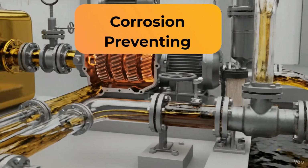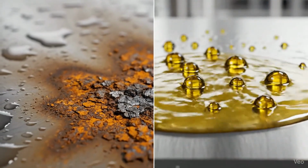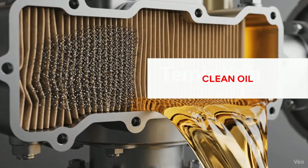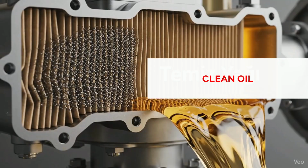Corrosion prevention. Oil prevents the formation of rust by cutting off the contact of metal surfaces with moisture and air. Cleaning. Oil picks up metal particles and contaminants resulting from friction and transports them to the filters. Thus, the system remains clean over long periods of operation. Turbine engines incorporate shafts rotating at thousands of RPM, high temperature zones, and numerous bearings and gears. Therefore, lubrication systems must lubricate such complex systems efficiently and effectively.